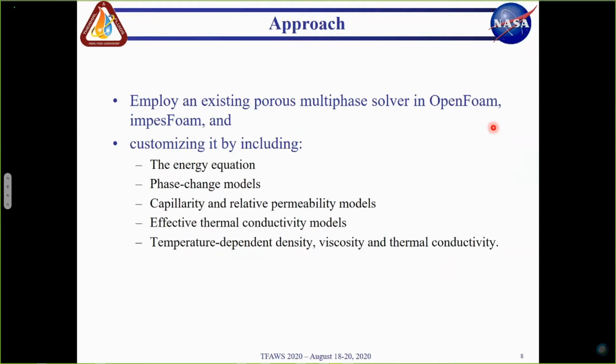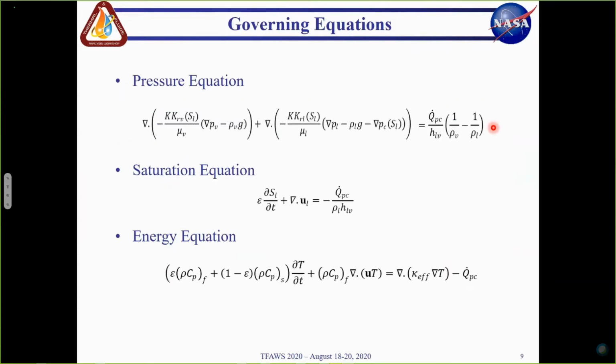So to develop a solver, at the very beginning, we employ an existing porous multiphase solver in OpenFOAM, which is called impesFoam. This impesFoam solver can perform simulation of multiphase flow in porous media. So we customize this impesFoam solver by including the energy equation, phase change models, capillarity and relative permeability models, effective thermal conductivity models, and finally we added temperature-dependent fluid properties like density, viscosity, and thermal conductivity.